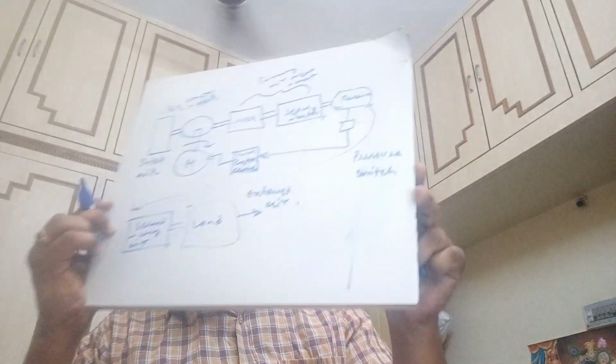Pressure switch valve. Okay, so those are the main component parts of a pneumatic system. Ideally, air in a system has a light oil mist to reduce chances of corrosion and to lubricate moving parts in valves.